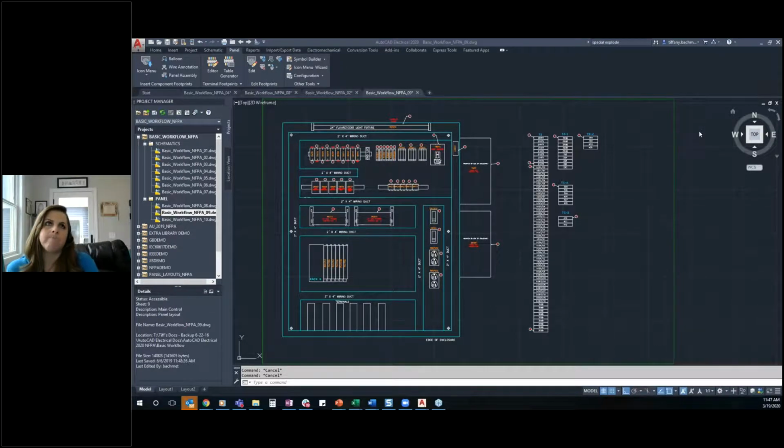But it will work if that drawing's a completely new drawing. So I'd like to have a command that essentially invokes that, or doesn't care if the drawing already exists in the project, because we're having problems of terminals becoming associated in two places, since we're using that copy function and overwriting an existing drawing in a project. Correct. But it isn't updating the terminal strip to be something different, so that it doesn't see it as being duplicated.